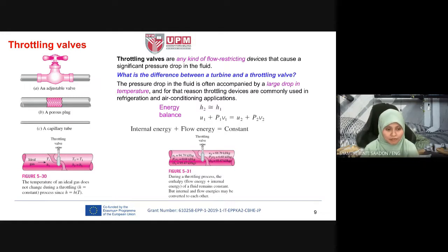For this valve, only temperature change and pressure change. But internal and flow energy may be converted to each other. So only the internal energy and flow energy change inside the valve, the system.